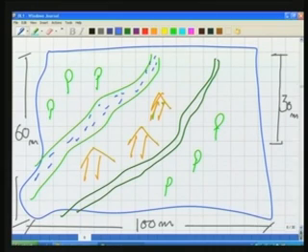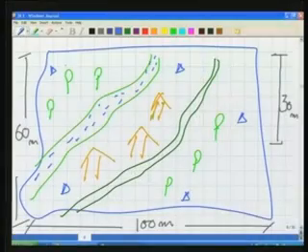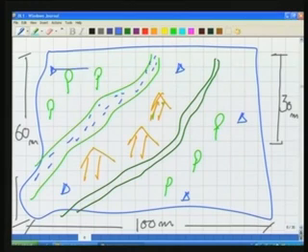Well, the control network could be, let us say that you establish a control network here, another point here, another point here, another point here, one more point here. I am considering here that it is possible for us to measure distance across the river using the tape. It is a small river and you can do it. Okay? Now, by doing that, what have you done? Your network will look like a network of triangles. We will explain this thing.